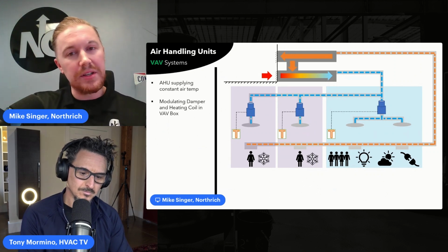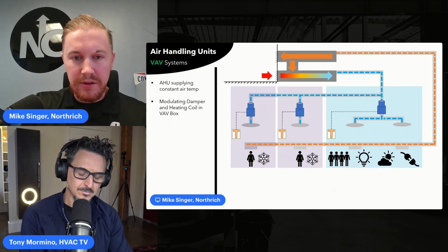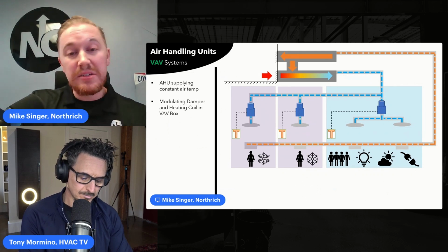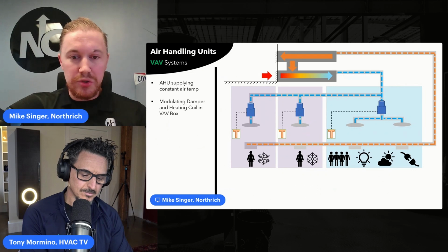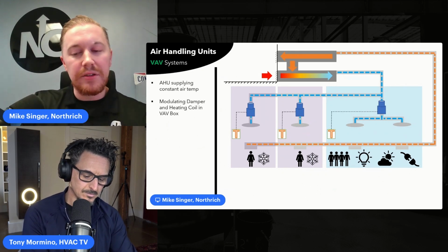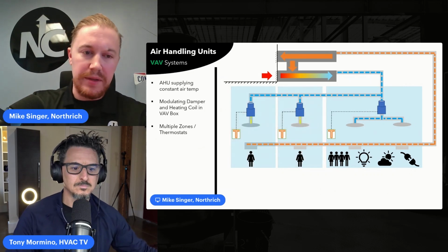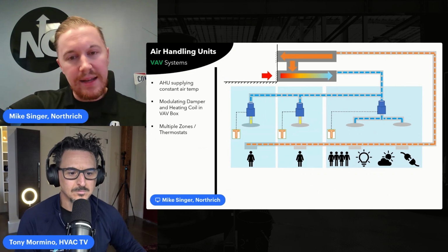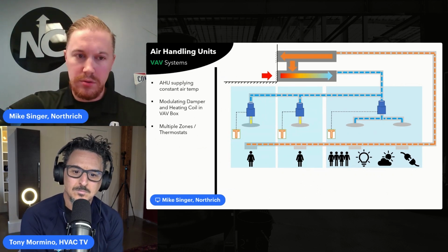So as we deliver 55-degree air out of the supply section of the air handling unit, and a space on the left of the screen that we see here might be getting overcooled, we will be able to rectify that issue by providing some heat and delivering nice, warmer or room neutral air to that space that's being overcooled. So independent temperature control for each zone.